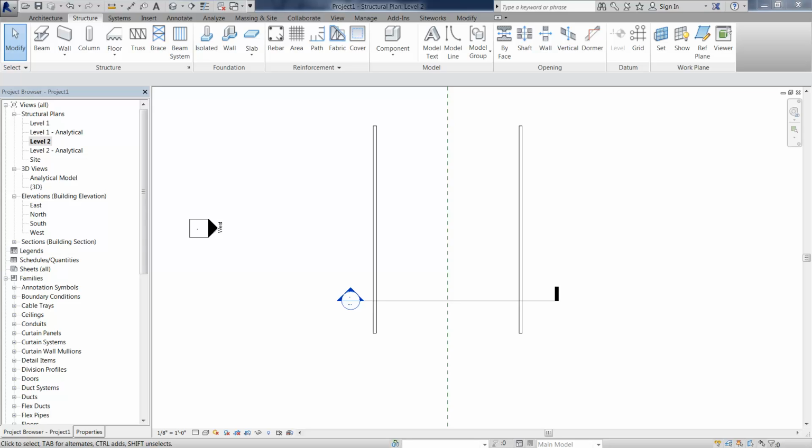If you're hovering over a wall, Revit will assume that, hey, I'm sitting on top of this wall, when it may not necessarily be the case. So in order to have your joist essentially stop and start at the edges of the wall, you need to have the angle in there first. That's basically the gist of it.